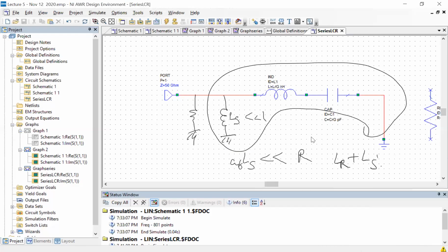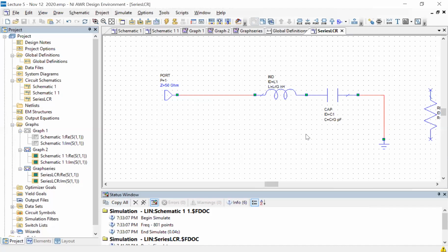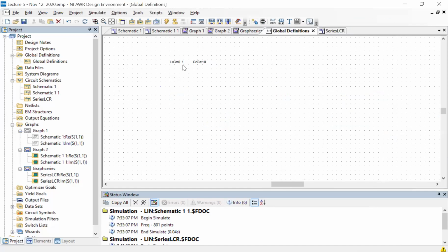Okay. So in fact, since we looked at this, why don't we actually see this in action right here? So I've actually never worked through this, but this is very cool. By the way, you can do the same thing even in the case of parallel case. You can put an inductor in series as well if you want. You just have to make a very large inductor in that case to get the same kind of impedance. So let's take the inductor, short this to ground, and this was what, 0.1 nanohenry.